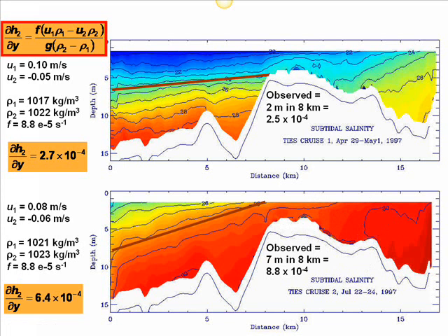Slower velocities. Slower velocities where? Here? No, here? So if there are lower velocities, you would expect weaker shears and less mixing. Weaker vertical shears, right? The slower the flow, the weaker the vertical shears produced by bottom drag. So there's more mixing here than here, right?